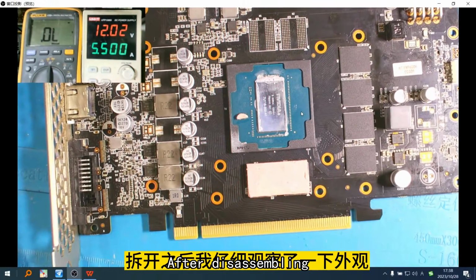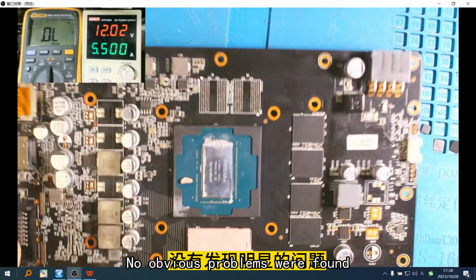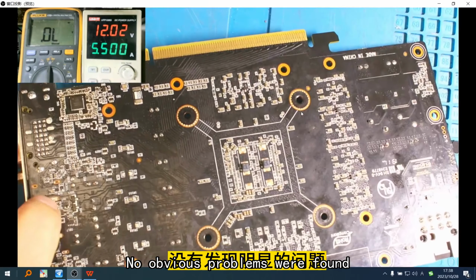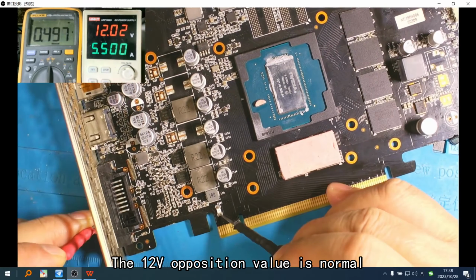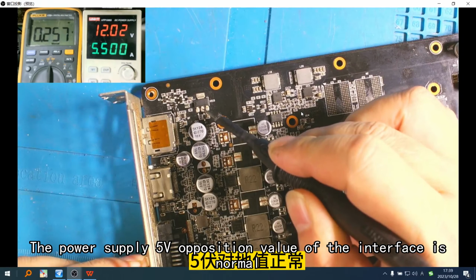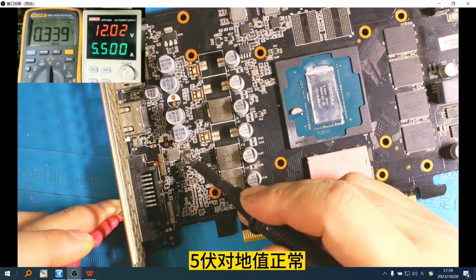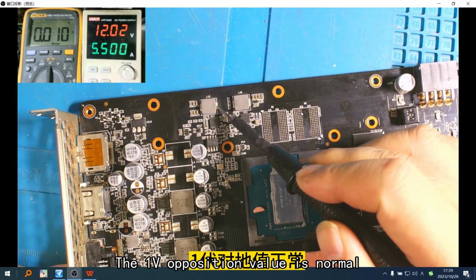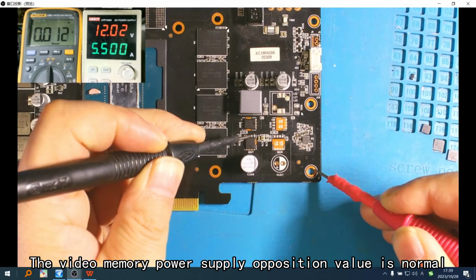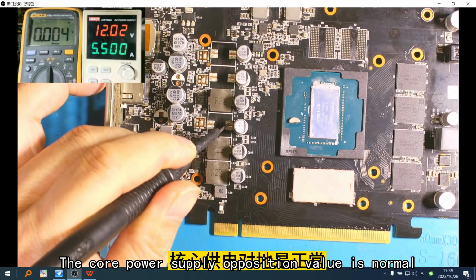After disassembling, I took a closer look at the exterior. No obvious problems were found. Let me give you a rough understanding. The 12V resistance value is normal. The 5V power supply resistance value of the interface is normal. The 5V power supply of the chip is normal. The 1.8V resistance value is normal. The ON resistance value is normal. The video memory power supply resistance value is normal. The core power supply resistance value is normal.